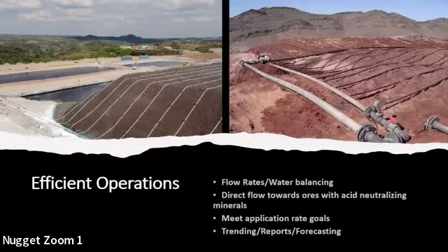They're still doing 25-foot lifts here, so under the 3 lift conditions, it should be fine. Which I should mention, maybe to head this question off now, is that our test work does focus down to about 80 feet below ground surface, between 70 to 80 feet below the heap surface. The reason is that in terms of your gold or copper recovery, those first few lifts are really where you should be getting the majority of recovery of the recoverable metal. So below that point, we don't focus as much. We're really just looking at those first 1, 2, and 3 lifts, because that's ideally where you're getting most of your recovery.